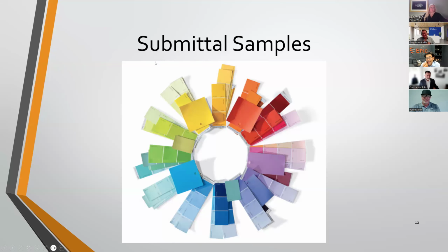One thing also, from a litigation standpoint and a defect standpoint, is understanding how vibrant colors are going to work in our South Florida environment. Super bright reds, really rich colors, those are not going to hold up. So much so that if you look at the fine print on even these worldwide manufacturers, they will talk about color fade and have exclusions for that, and attempt to say that the fading is not going to be representative of a failure of the product. So just be mindful that you're not going to get the performance out of a lime green as you would from an off-white.